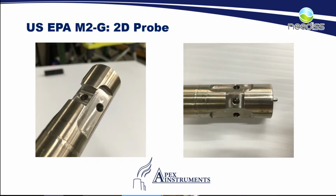But what the method 2G would give you would be a more accurate flow determination when you make your calculations for your mass flow rate, how much emissions is actually coming out of the stack. So it can get a little bit complex, but I just wanted to point out that this is a standalone method and it would not be used during a method 5 or a method 29 for metals or any other isokinetic method.